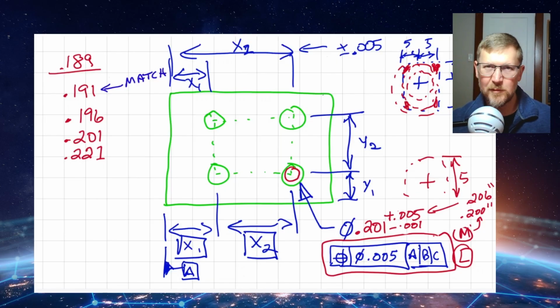There may be exceptions to that, but that's such a tight fit. You probably want to start with a pilot hole that's smaller, get the parts kind of lined up so you can see where they're at, and then drill the whole larger hole up to size that's at the same diameter in the right location already. So you don't have to worry about positional tolerances factoring into this.